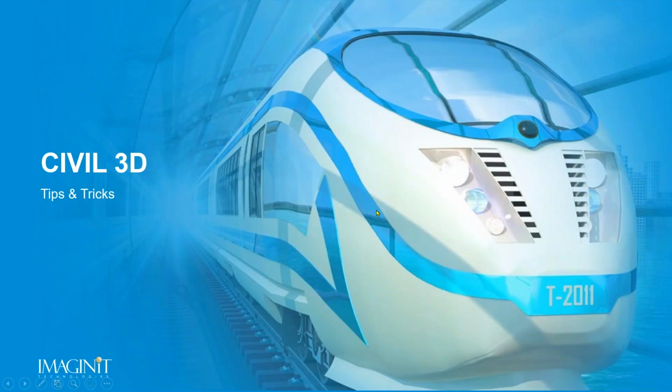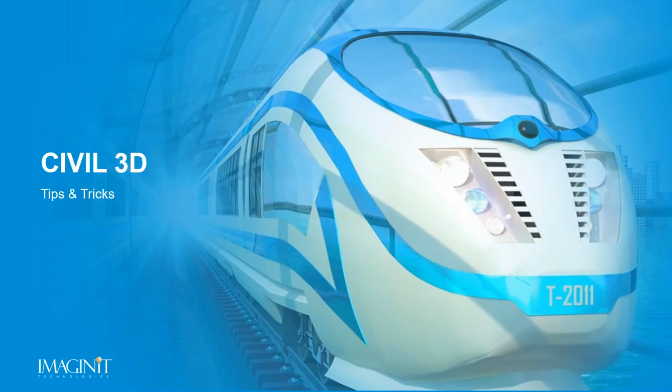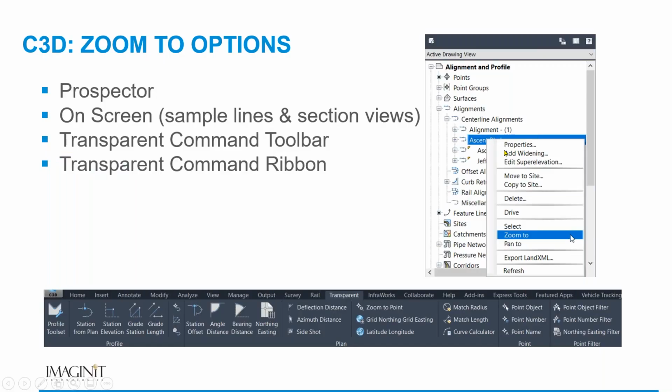That was really dealing with Map and Civil. Moving forward, we want to talk about Civil 3D here. And I have several tips and tricks working with Civil 3D. First is zooming to objects. I like the option to zoom to object from the Prospector command, or nowadays from the transparent commands.